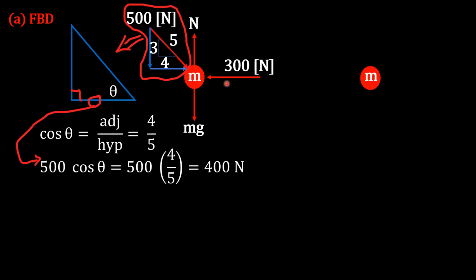So this block, we're assuming that it will move to the right-hand side with a force in magnitude of 10 kilogram times acceleration, mass times acceleration. And as a convention, we always make sure that the positive x-axis is in the same direction as the moving particle. So here we have our free body diagram.